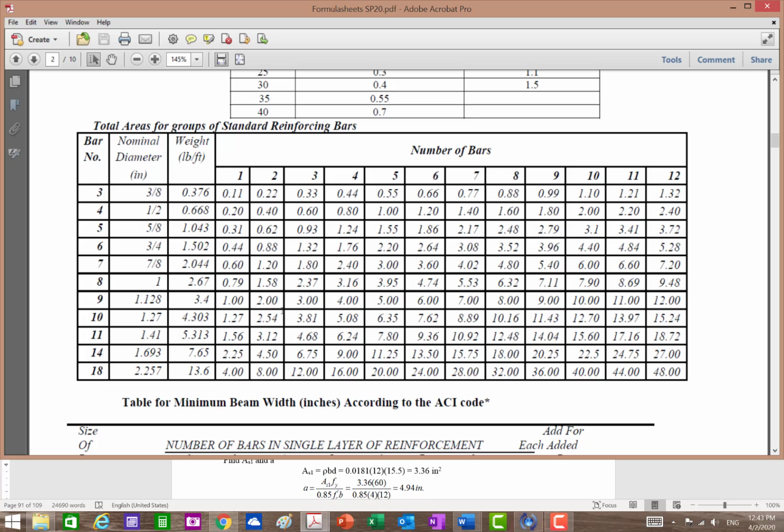That's a little less now than, wait a minute, that's 4, no. Yeah, that's 581. So it's less than 6. So you're putting less area of steel. So that will reduce the problem that you have with your ductility, right? So you can reduce then the amount of steel by using a combination of bars.